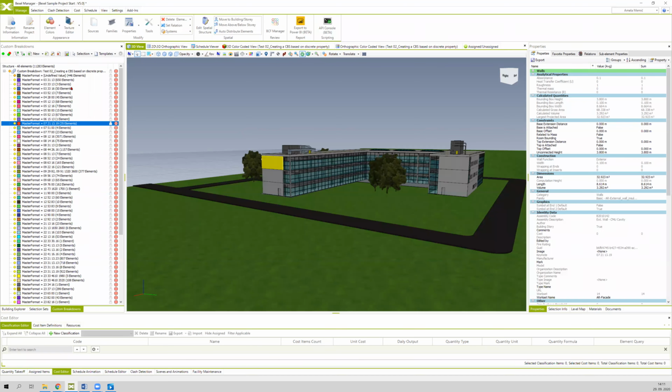Further on, you can also review if you have any elements in your project that do not have a certain property, which is really important in further steps, because as you create several different BIM analyses on the basis of a certain property, and if you have elements that do not have this selected property, then your BIM analysis will not be properly done, because it will not include all elements of the BIM project.